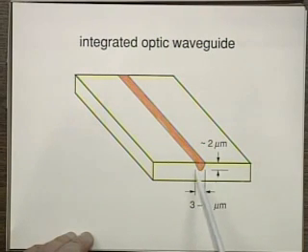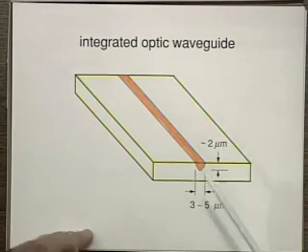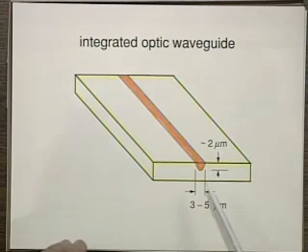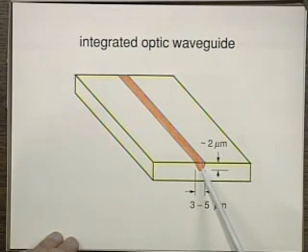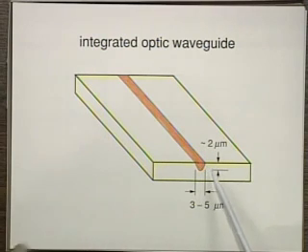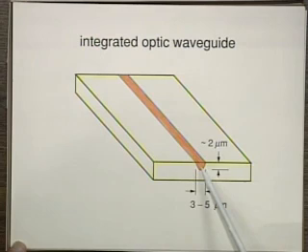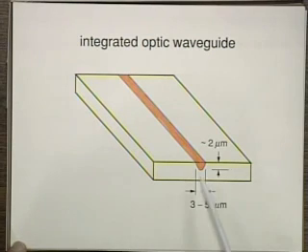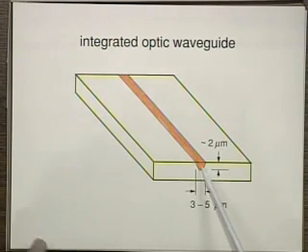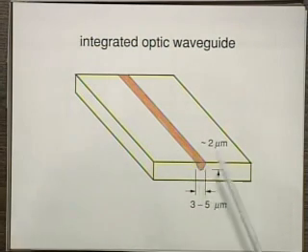And if this is controlled, then using photolithographic techniques and so on, you can raise the index over here. So if you look from the side, you have a material that has a little higher index than the cladding over here, and then you can propagate light down this waveguide. The light is guided through the waveguide, just like in a fiber, because the index here is higher than the ones on the side. And then you can coat this and protect it and so on.